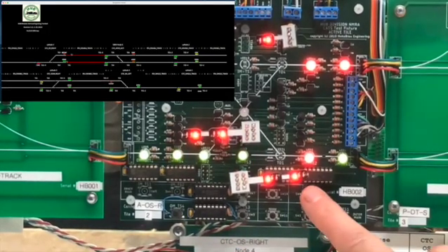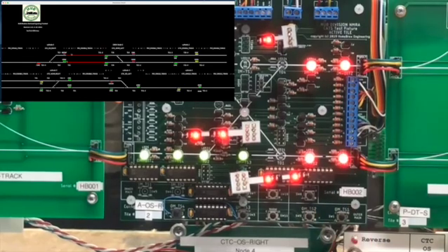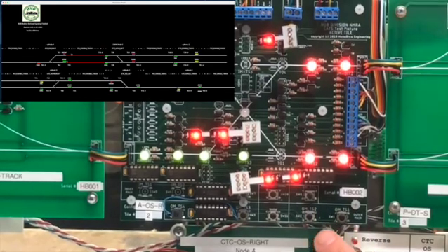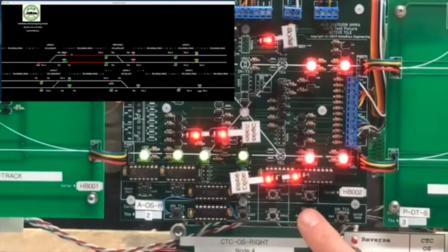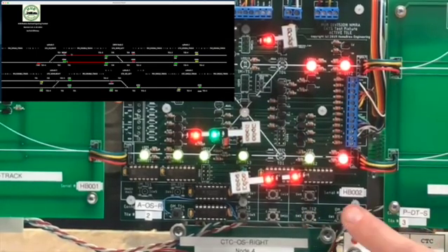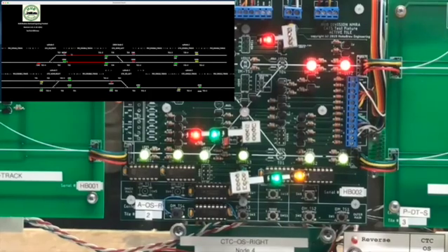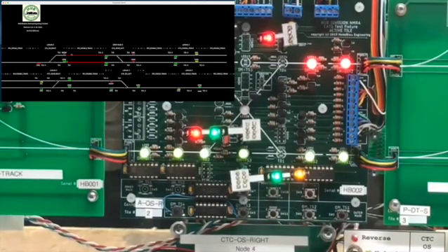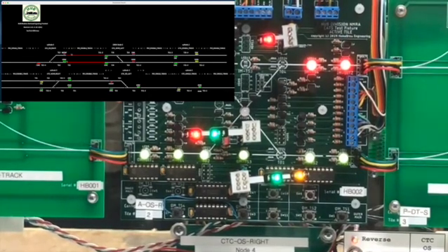Watch the CATS panel as Train T1 occupies the blocks in this module and proceeds forward. CATS uses the occupancy information to follow the train movement and update the display. In this example, the only thing that indicates train direction is the order in which the blocks are occupied as the train moves. CATS also updates the signals based on the ABS signaling rules.